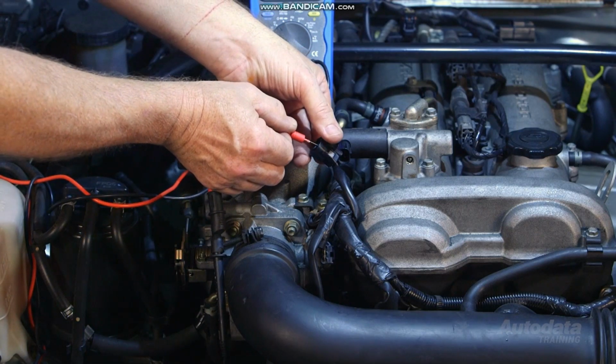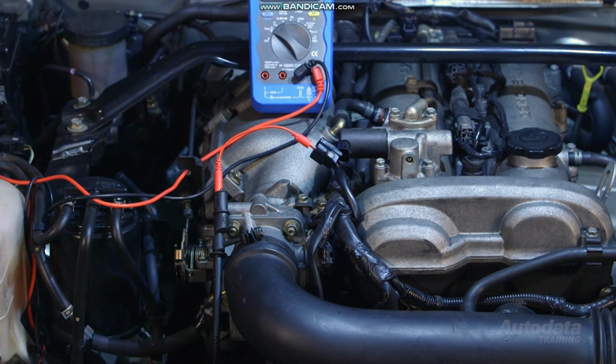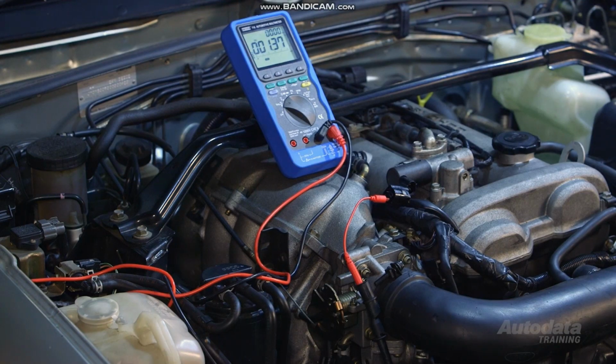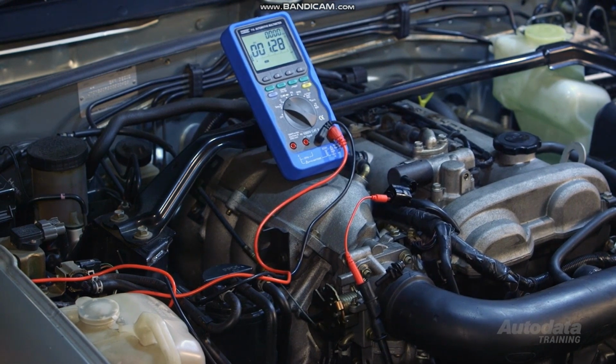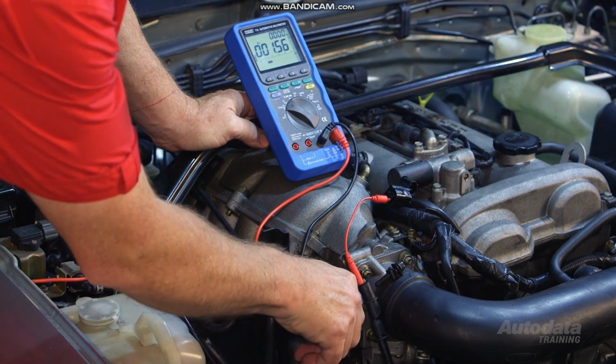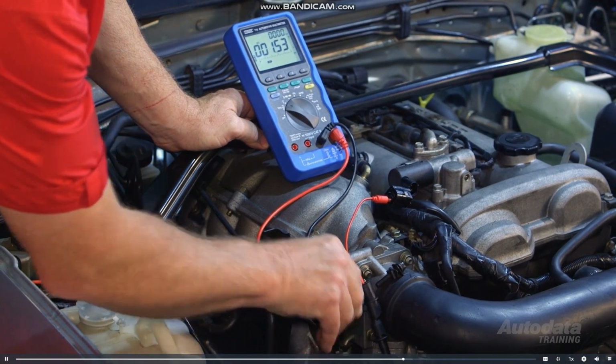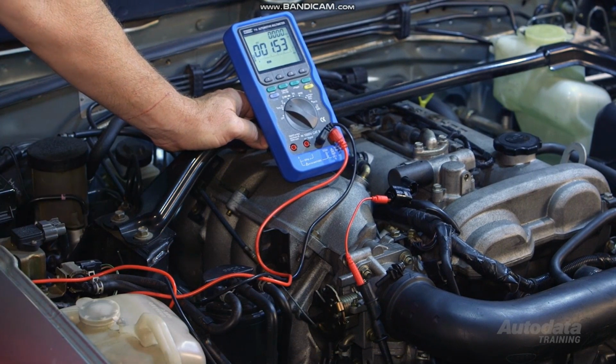Connect a multimeter to the actuator connector control terminal and battery positive. To get a reading, you will need to trigger the actuator with the scan tool, if yours has this feature, or by starting the engine and increasing the RPM by quickly opening the throttle. You should see a voltage change when you increase the RPM.